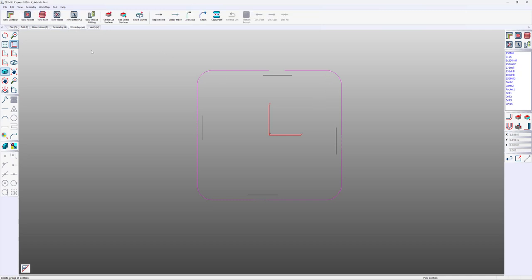Remember that curve was still active. I didn't delete it, I just cleared the links. So I'm going to go to linear move. Now I want to pick the end over here so I get exact snapping, so we'll snap to all. There's my line. We're going to wrap it over to this point here. Okay, now we've created our curve.